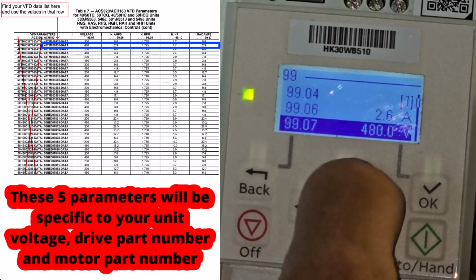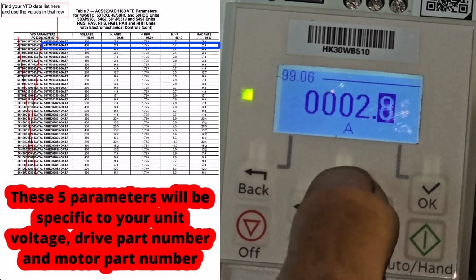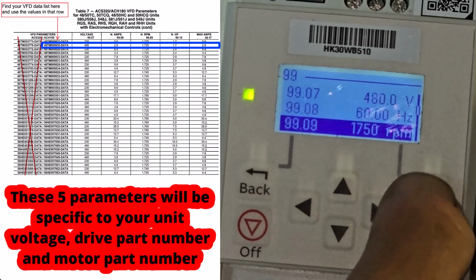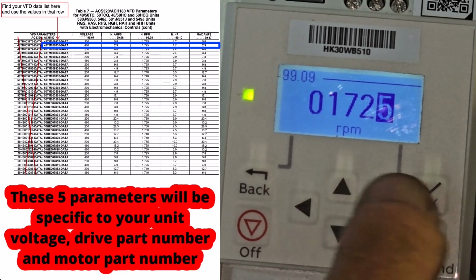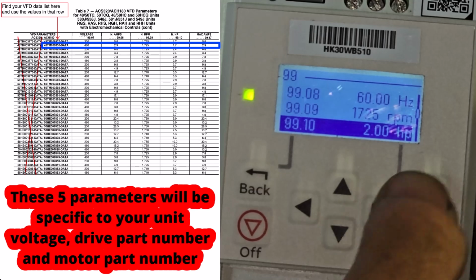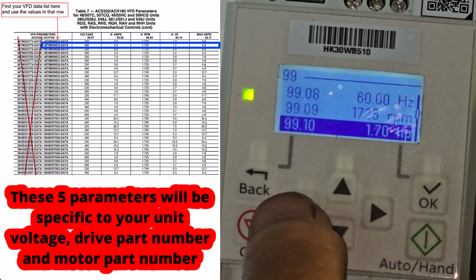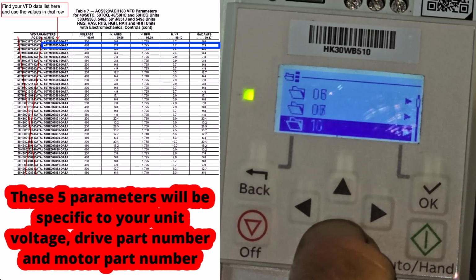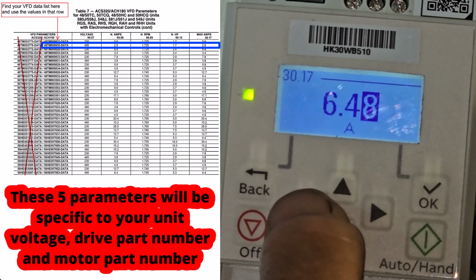Now scroll to 9906 and enter 2.9 for motor nominal amps. Scroll to 9909 and enter 1725 for nominal motor RPMs. Scroll to 9910 and enter 1.7 nominal motor horsepower. And finally, exit and scroll to group 30. Scroll to 3017 and enter 2.9 for motor max amps.